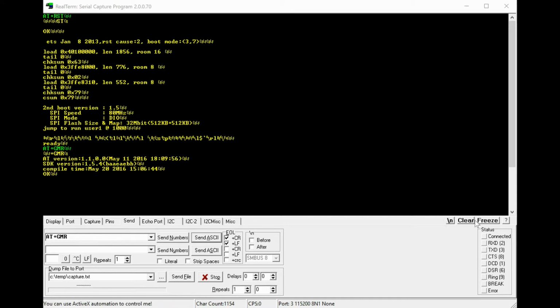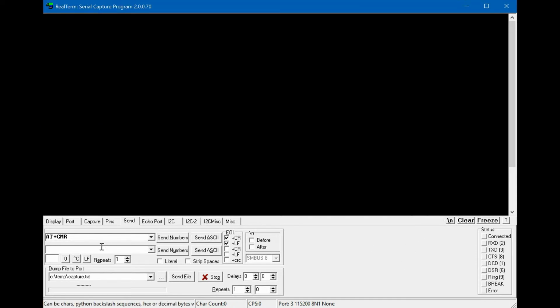By default, the ESP8266 stock firmware is set to access point mode. If you would like to confirm that, send the following command. You should get this response with the actual mode, where 2 corresponds to AP mode. We can query actual default parameters for connecting to access point with the following command.